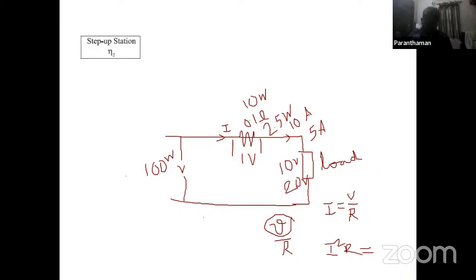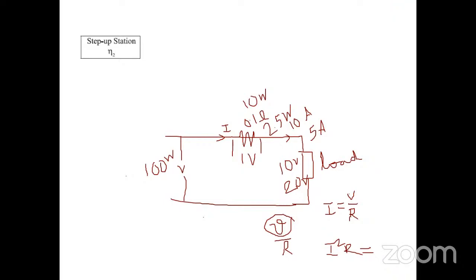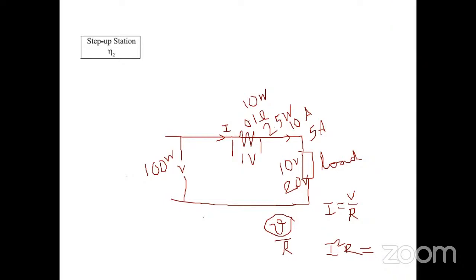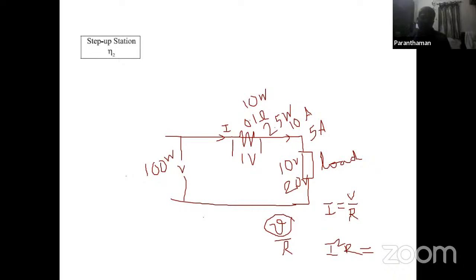In this case, I just want to add one more thing, sir. I told in the first class also, the nameplate details of your motor. For 10 kilowatt, what does it indicate? Mechanical output. Exactly, that's the shaft power output. That is the useful energy we are getting from the power supply. Is there any doubt, sir? This is the end: shaft power output is the end. Generating end is the generating power station. So we have to calculate from this end to that end.